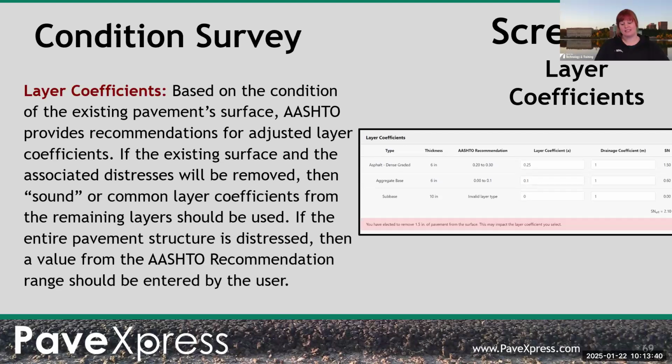Okay. And then the last question here for a little bit is, what is the minimum thickness of existing HMA that you want to remain when you're doing a mill and fill? Is there a rule of thumb? Is it like 2 inches? That again depends on what my total thickness is. But you'd probably want at least a couple inches left.